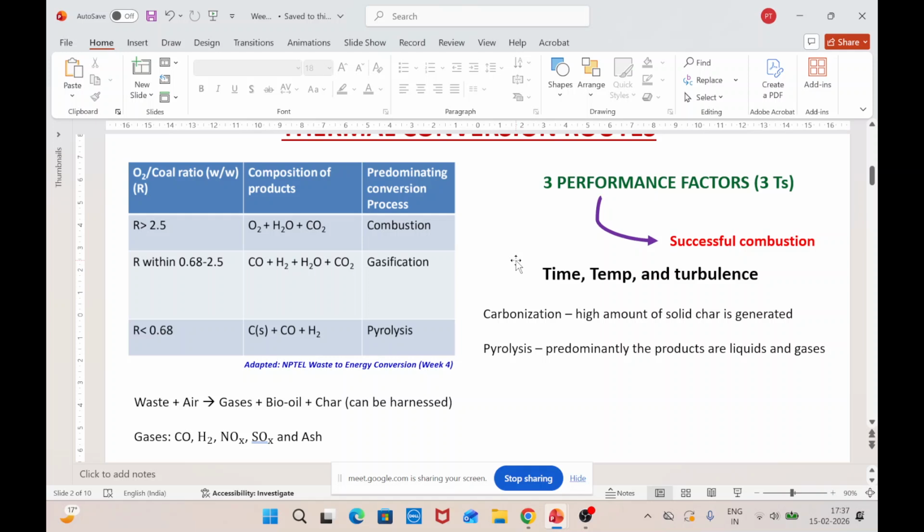You make the bio oil react with some alcohols, or you do more sophisticated processes such as catalytic deoxygenation, where you try to remove oxygen through a catalytic process. Typically you do this catalytic deoxygenation either through the hydrotreating method or through the catalytic cracking method.